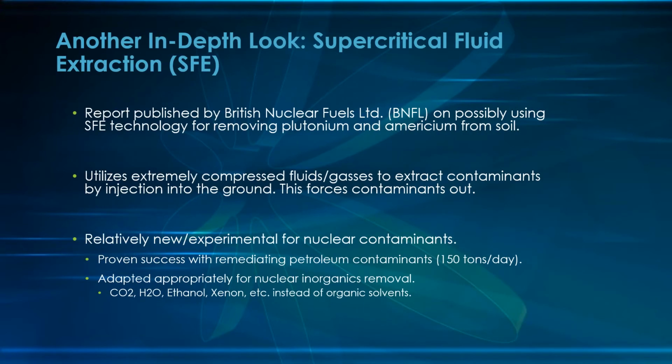So just as in situ grouting involved injecting particulate matter into the ground to effectively surround and trap contaminants in the ground forever, I also considered supercritical fluid extraction another remediation method in my report because it had a unique characteristic, which was the ability to remove nuclear inorganics from the ground, specifically a report published by BNFL for removing plutonium and americium from soil.